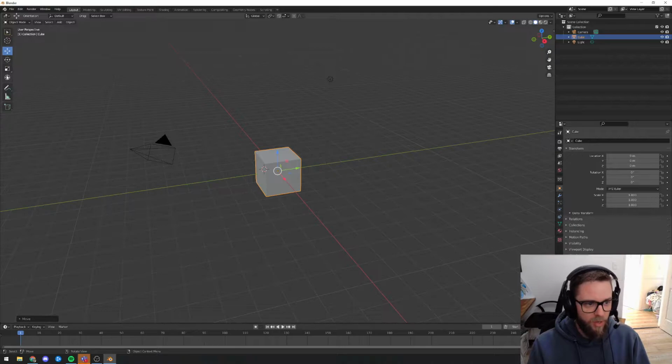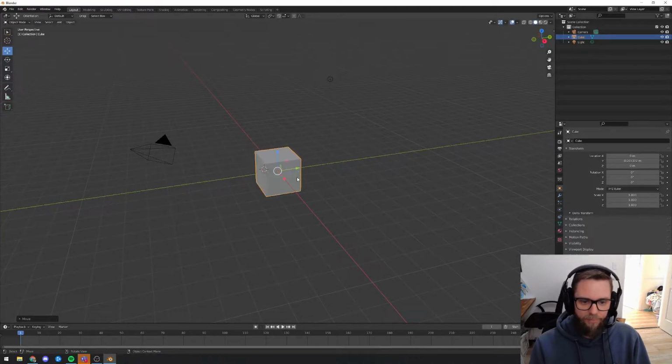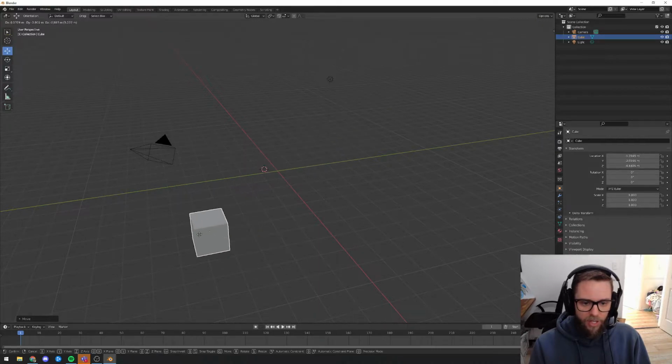We've got a few tools here. This one is used to move an object along an axis. When you click on this, you get these 3 arrows. The blue one to move up and down, the red one to move along this axis, and the green one to move along this axis. And if you click on those arrows, it allows you to move an object along the axis of the arrow that you've selected. If you click within the circle there, it's just free move.